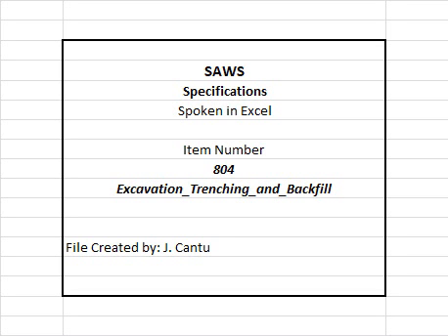5. Sanitary sewer backfill. A. Bedding material. 1. The existing material at the bearing level shall be removed and replaced to a minimum depth of 6 inches or 1/8 of the outside diameter of the pipe, whichever is greater, with bedding material. 2. The bedding material shall extend up the sides of the pipe sufficient to embed the lower quadrant of the pipe. 3. The bedding material shall be composed of well-graded, crushed stone or gravel conforming to the requirements of Table 2 unless modified by the engineer in writing.